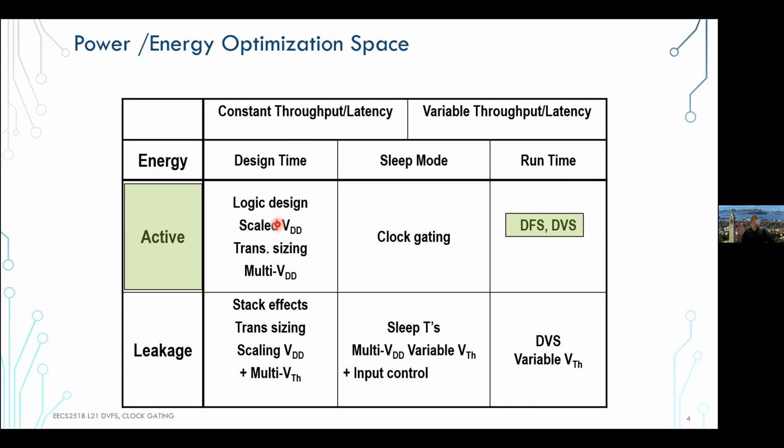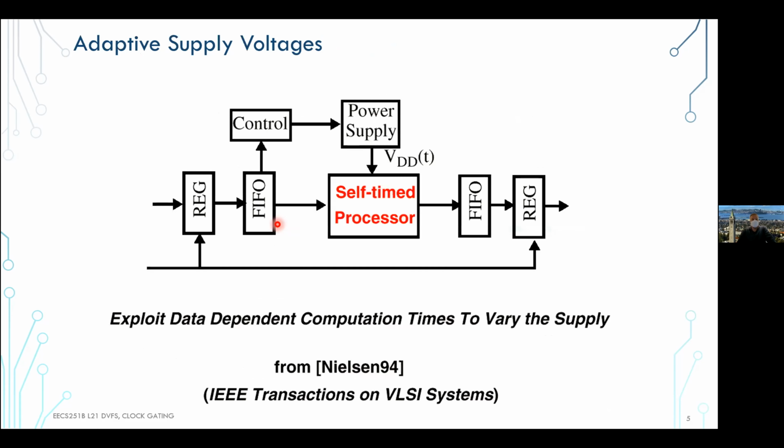And a lot of these things basically originated here. You can go back roughly 30 years and see how the whole story developed. So, early 90s, people were thinking about dynamic energy, where you have C V_DD squared. That's your term. And so C is nice to optimize, but if you can move V_DD, that's a square win.